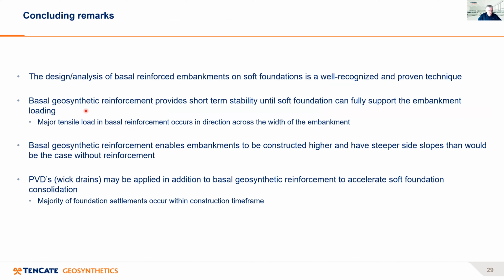So some concluding remarks. I think the first thing I want to say is that the design and analysis of basal reinforced embankments on soft foundations, it's a well-recognised and proven technique. The basal geosynthetic reinforcement provides short-term stability until the soft foundation can fully support the embankment loading. And in this particular case, the major tensile load in the basal reinforcement occurs in the direction across the width of the embankment.